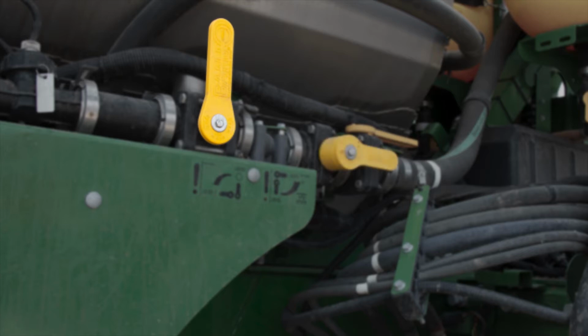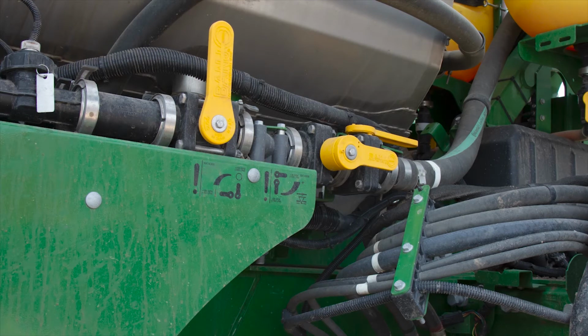The middle handle is one to operate in a high flow mode. So again, if we're in this case operating in standard above 26 gallons per minute, we leave that orifice valve where it is. The final valve in the system there is basically a boom shutoff, just an open close valve, and allows us, if we're going to do any work on the boom, that we don't have a straight line from the solution tank through the pump out of the boom. So we can shut that off if we do need to work on anything. Like the flow meters, for instance, if we spray something like atrazine or a dry soluble chemical, we can shut that off so we're not allowing additional fluid into the system if we're working on it.